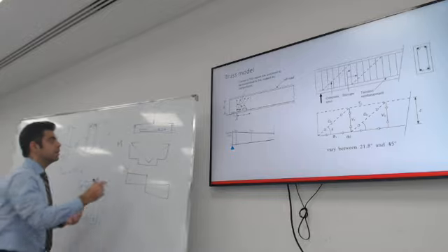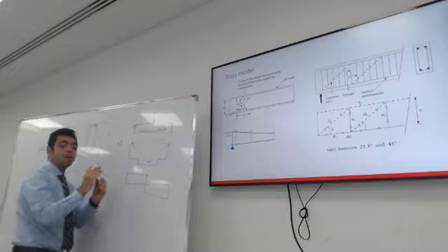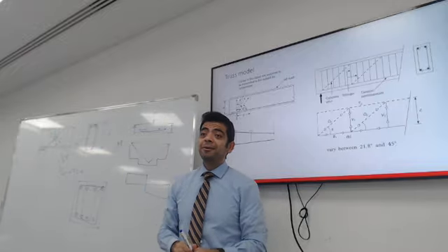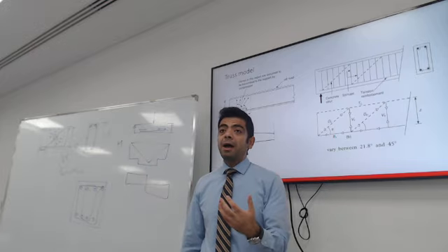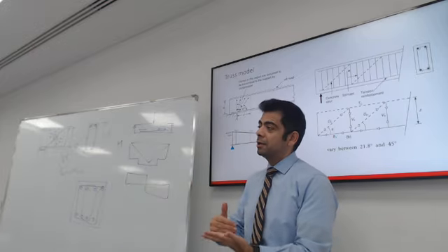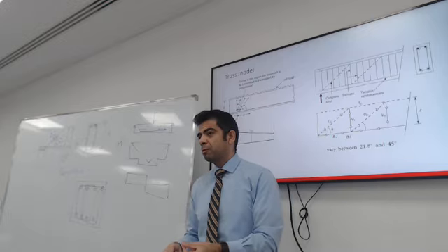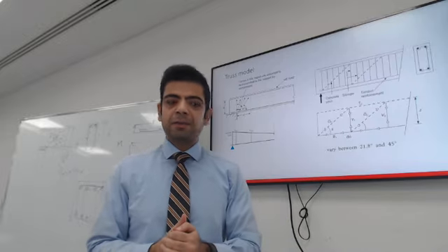And you basically offset the moment curve to deal with the tension reinforcement this way. And we can also calculate the additional tension that goes into the bottom reinforcement, so we can make sure that the bottom bars can take the load.